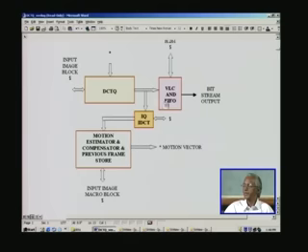And regarding this I-frame, we apply block by block, out comes the I-frame here which is stored. It is also transmitted after doing VLC and via first in first out, typically 16 kilobits depth should be enough for FIFO storage, and out goes the bit stream. If rate control is in place here, then you will have a constant bit stream here, and this is the video encoder, and that will be at the receiving end.